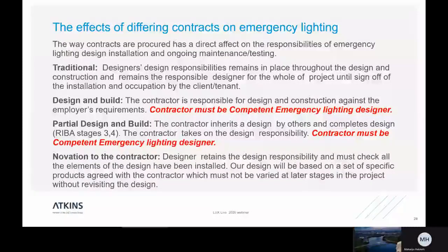If you're asked to do an initial concept, then you cannot be the competent emergency lighting designer, because you are not making the final decisions on equipment and the nature of the scheme. So the contractor must be that person. Partial design and build, where you do it to a stage, you need to be very careful about how you hand over to the contractor.